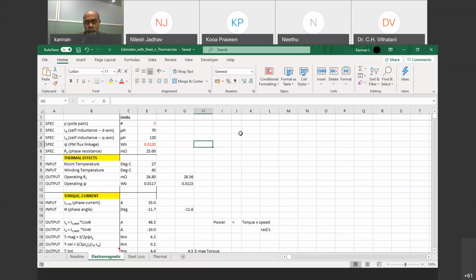If it's a good motor, I'll find a sinusoidal waveform. If it is not very good, it will be a slightly distorted sine wave, maybe with some noise and spikes thrown in. And if it is what is called a BLDC motor, it will be a very badly shaped wave. It will be like a sine wave that is made of steps, 3 steps up and 3 steps down.